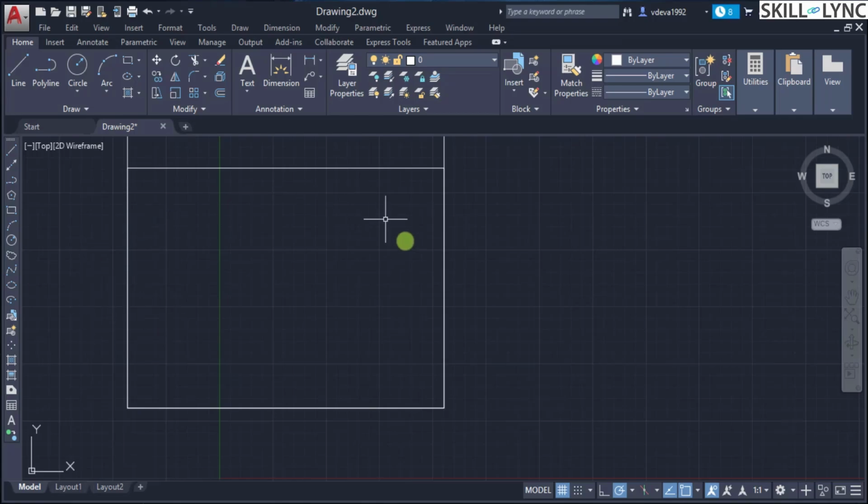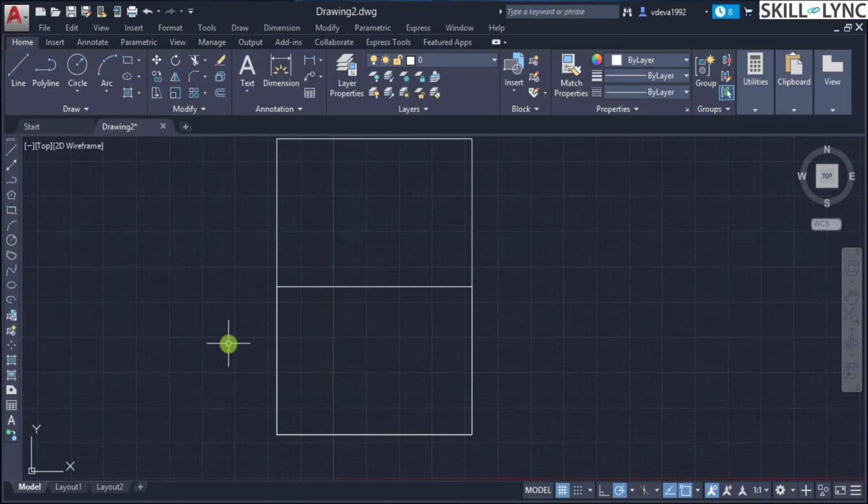This is where we'll be using the zoom functionality. So let us quickly use the zoom all command. So I'm invoking the zoom command by Z, and then I'm using A to specify all. Okay, now the screen window has been resized to make the entire object visible. So now this is the A3 paper that you can see here by unfolding an A4. So typically it means that placing two A4 sheets side by side along the breadth will give you an A3 paper. So now let's repeat the same step for an A2 size.